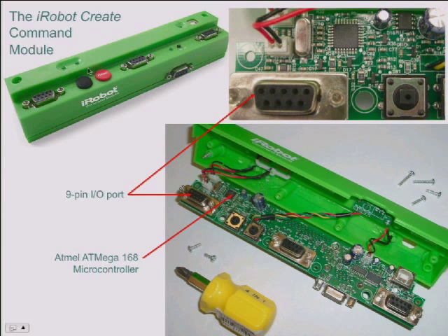And playing audio tunes, that's right. So this device has a little piezoelectric speaker on it, right? The way that works is you make sounds by turning on and off a voltage at a certain frequency, and you can make it buzz, you can make it play certain tunes. If you get the frequencies right, it'll sort of sound like a musical sound, sort of. Not a particularly pretty one, but yeah.